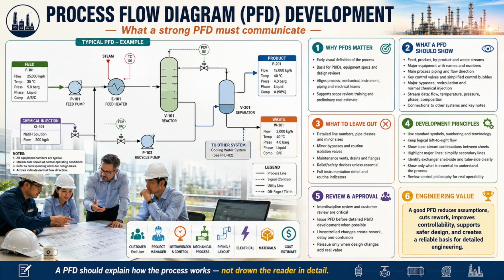Exchanger representation must be technically clear. Identify shell side and tube side streams wherever possible. When the allocation is still undecided, use a neutral exchanger symbol rather than inventing a design decision. Represent a multi-shell exchanger with one main symbol and suitable shell designations. Use equipment suffixes consistently to distinguish multiple shells from identical exchangers operating in parallel.